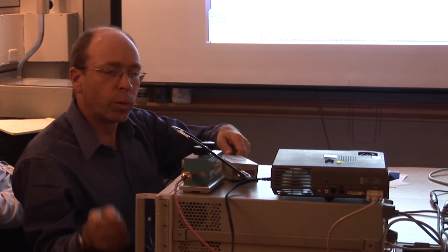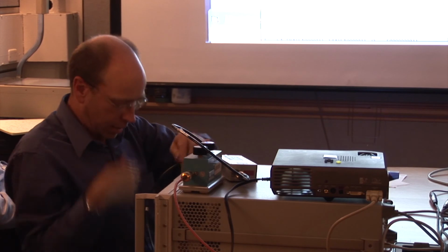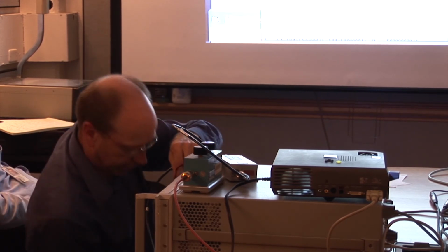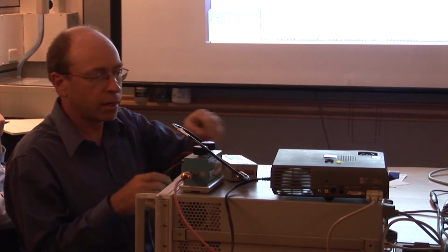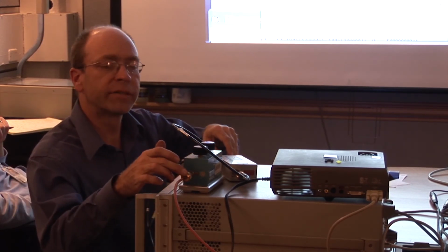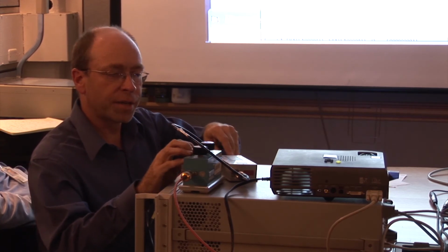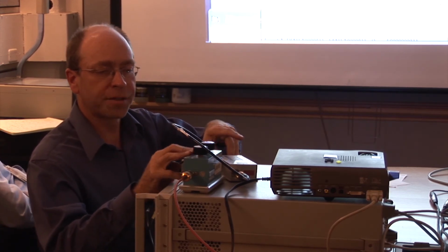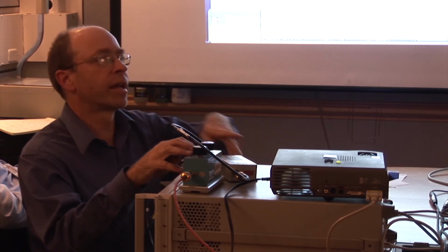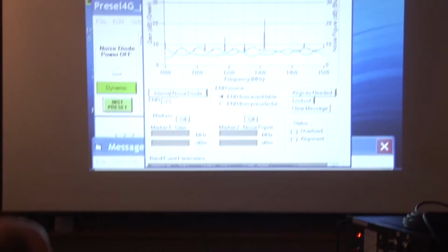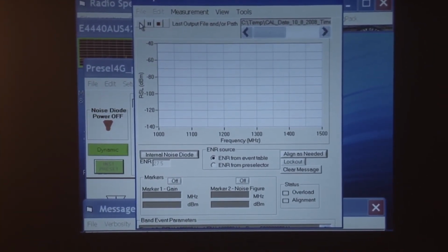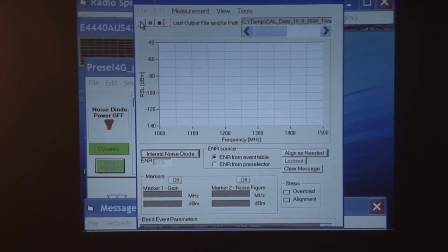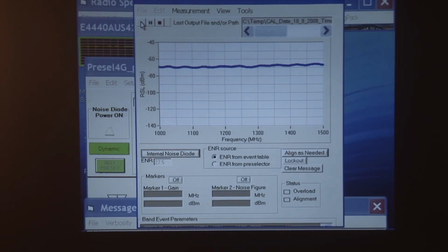Now, we'll go ahead and plug this in. The second amplifier, higher performance amplifier, which means lower noise figure and higher available gain. And I'm just looking here to make sure I've got everything hooked up right. Yep. Again, it's in the same places as the first amplifier. It's at the bottom, as it were, of our RF line, just at the input of the spectrum analyzer. Randy, if you'd do the honors, please. Diode on. Gather the data points. Diode off. Gather the data points.